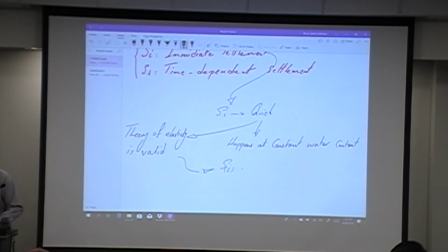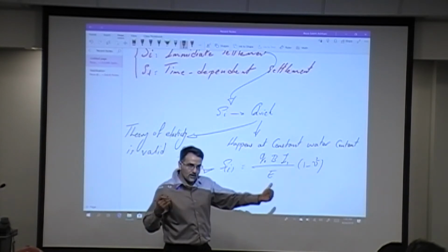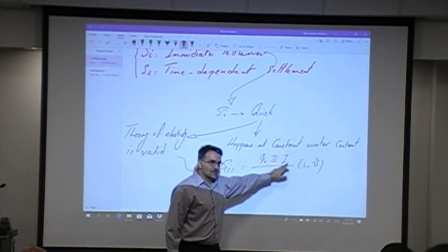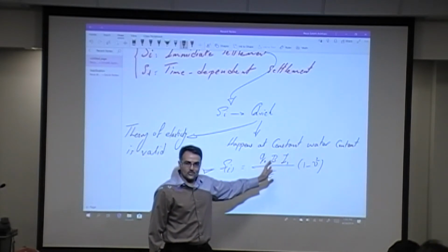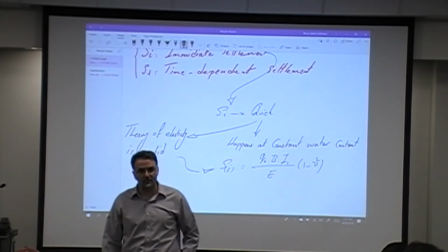We'll talk about that hopefully in our next lecture, but you can essentially calculate that as a function of distributed pressure at the surface, the width of the foundation that you have, or the loaded area, and you have a parameter here, and we'll talk about what that parameter is. Elastic modulus and Poisson ratio, right? This is the distributed pressure that acts on the material. B would be the width of the loaded area. I sub S is called shape and rigidity factor. Shape and rigidity factor, table 10.4 in your textbook.